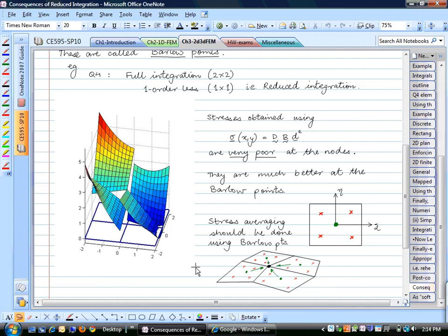The amount of discontinuity, you mean? Yeah. Not necessarily. That amount of discontinuity could be problem dependent. If you have some sort of a singularity, or if your element is closer to a crack edge or something, you might get huge discontinuity. But anyway, you would have to find some sort of an average to calculate stresses at nodes. Then you can plot your average stresses.